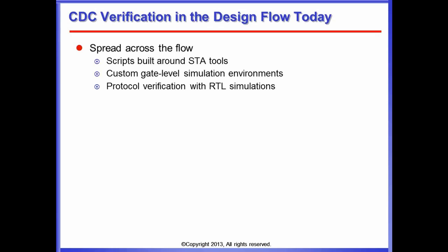They try to do this with a gate level simulation environment, moving edges to provoke the metastability and see what happens with the design. I have some who just have some kind of mechanism to identify these CDCs, and then they do a visual check of the whole thing, and if the designer says it works, it's going to work.